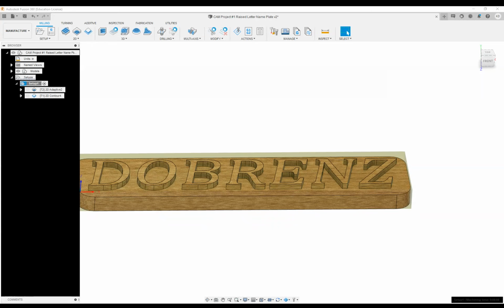Sometimes I will move operations around, and I don't have access to my Fusion folder, but I can use a notepad file, and I use the tools to kind of tell me whereabouts my operations begin and end. So if I were to Control F, let's just say tool 2, let's see where that happens. So it only occurs twice, which it should. So there's one at the beginning here and one at the end.